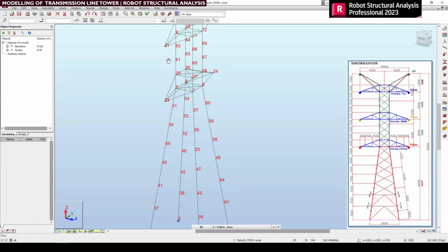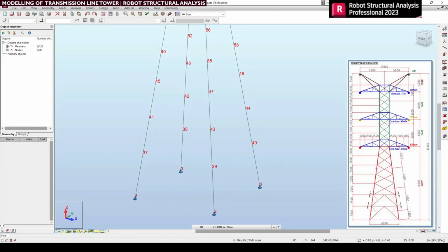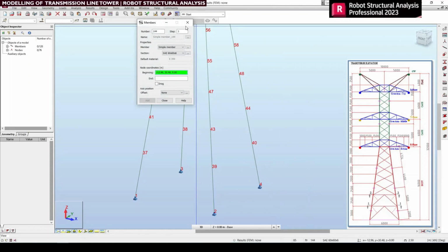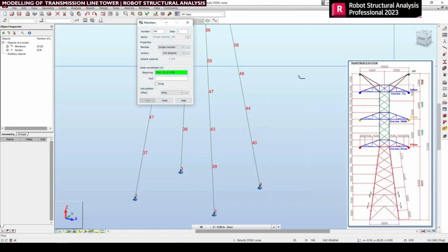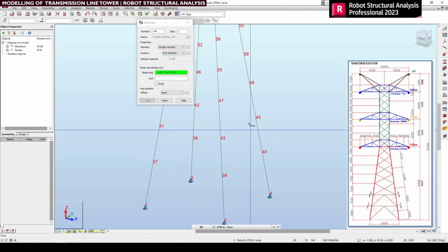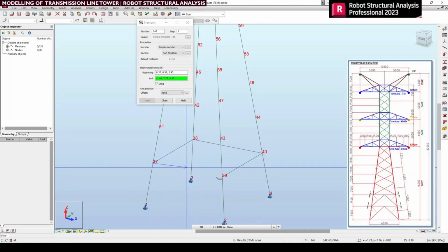Now we can start drawing bracing members. In the picture you can see the first bracing is going to be drawn at the 3.5 meter level as a horizontal member. So we need to select the member icon shown on the right hand side, the fourth icon. We can choose 60 by 6 at present. Later, after doing the grouping, we can assign the member sizes again with the exact sizes we need.